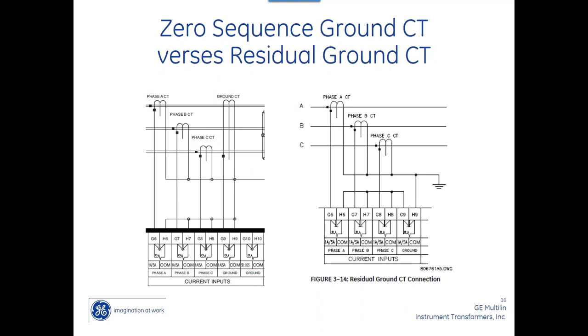Yeah, but it's negligible because you've got resistance. So there is a slight loss in that. Okay, if I've got a CT that goes around all three phases, the current's going out and the current's coming back, what should this sum be? Somebody want to tell me? 0. Very good, Chris. So we use that to see if I have part of the current going to ground.